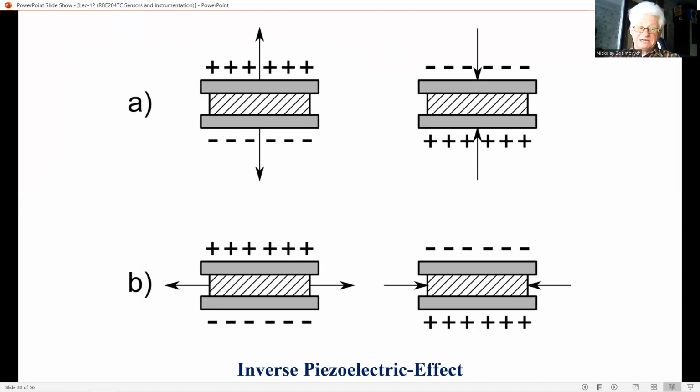A piezoelectric ceramic sensor, usually 1 millimeter thickness, measures vibration in a particular part of the construction, and a stack of piezoelectric actuators, 4 millimeters thickness, generates a counter movement in the same part of the construction. With a proper design of the control loop, the amplitude of the dominant vibration mode is reduced by a factor of 7.